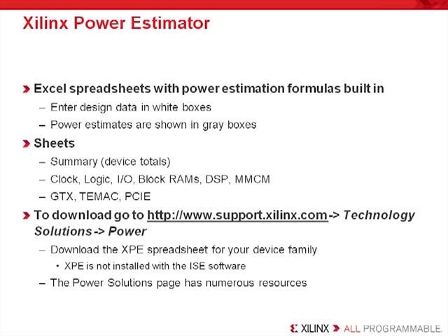To help you with that, we have several free recorded e-learning modules at support.xilinx.com which explain how to optimize your code and optimize your design for your device architecture. Writing good HDL is of course important because it is used by the synthesis tool to infer the resources. Since there is very often more than one way to code effectively for the same functionality, it is important to understand the differences between the two, and of course use your schematic viewer to verify that you're getting the resources